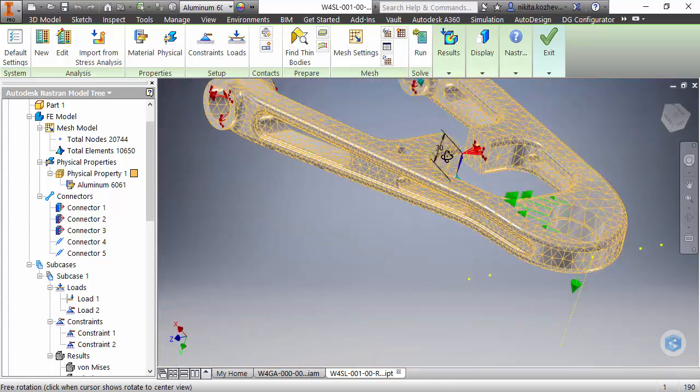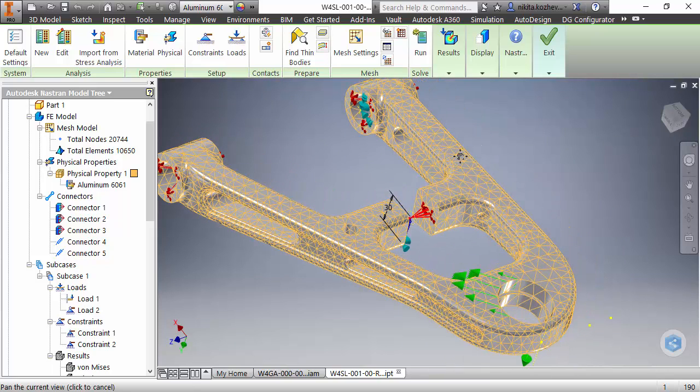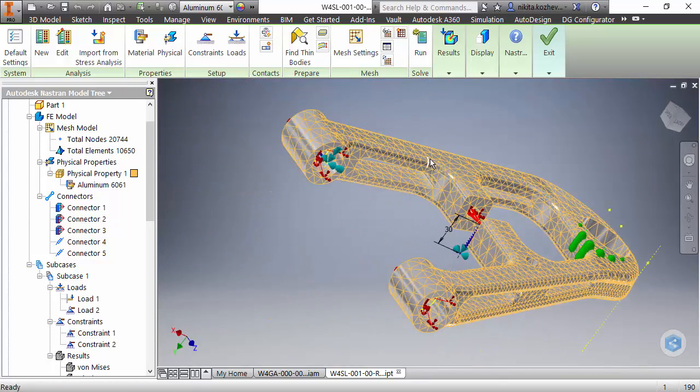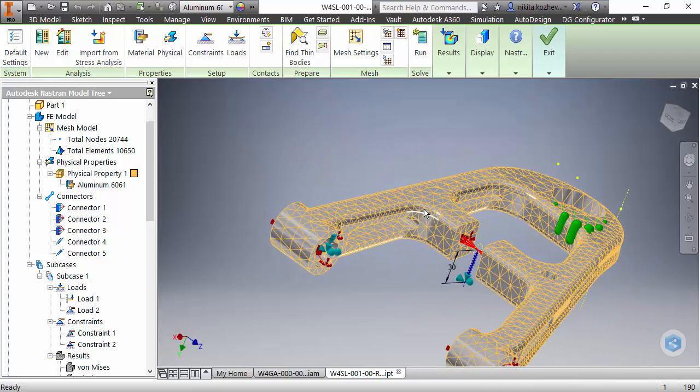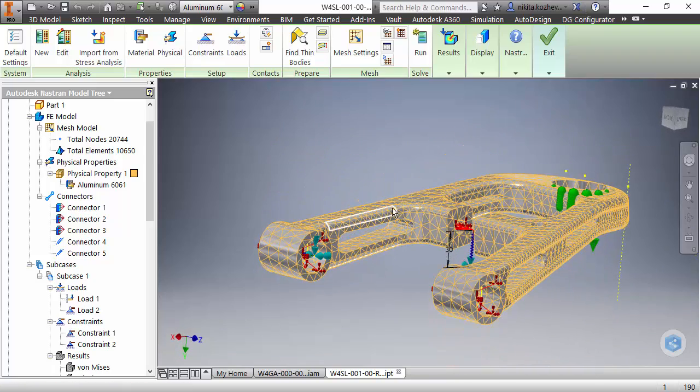The approach here is to reduce the mesh size in order to compare the two results. If there is no change in the maximum stress in the area, we can say that the mesh resolution is good, and no other improvement is required.